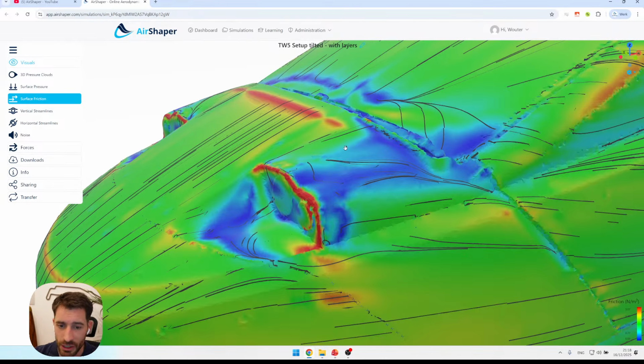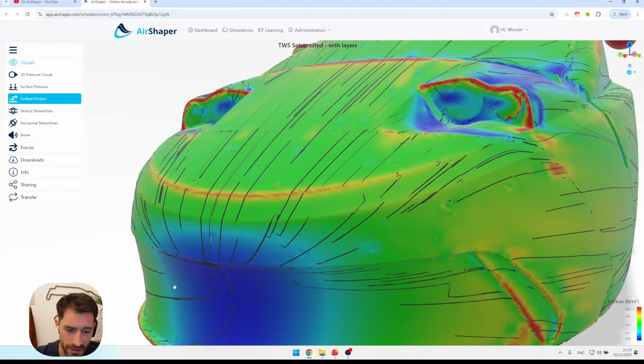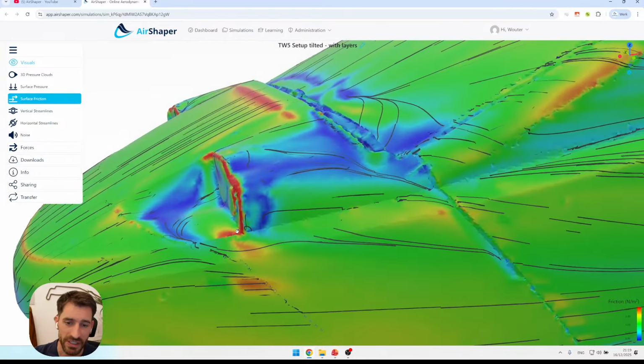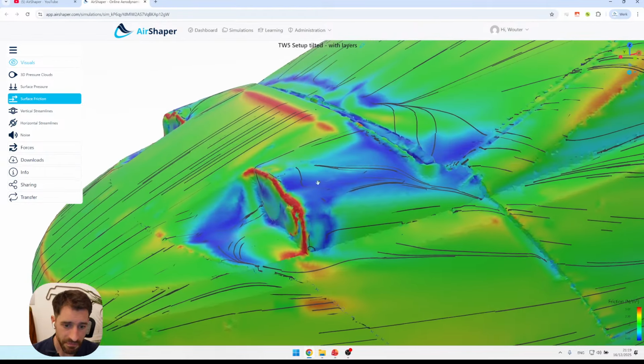So when you see low surface friction areas, usually it's either an indication of stagnated flow, which is still attached at the front of the car, gets squashed against the nose and then spreads out again. That's not a problem. But if it's in the wake of a sharp edge, for example, this indicates separated airflow and is a warning for you or a trigger for you to look upstream to analyze why the flow actually separated in the first place.